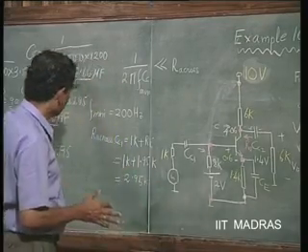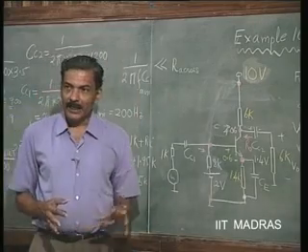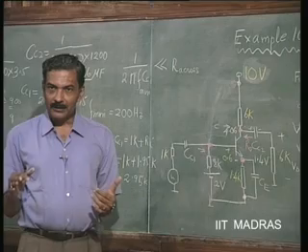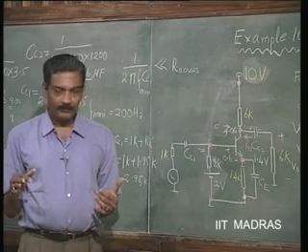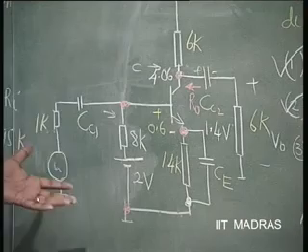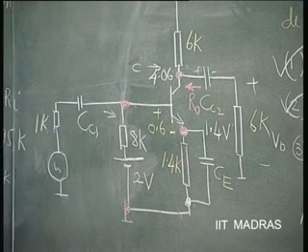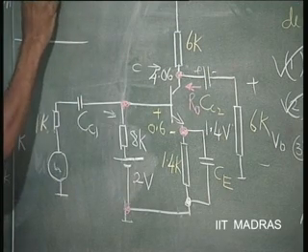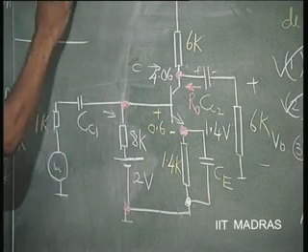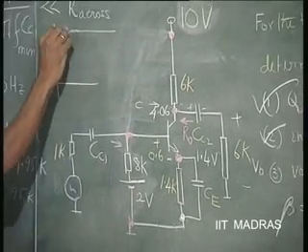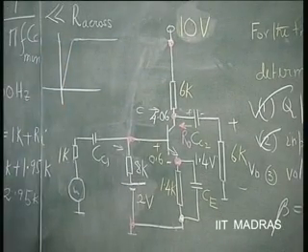So, they will reduce the gain, and that will bring about a poor lower cutoff frequency. If this kind of design is done, it will assure that up to 200 hertz the gain is not reduced at all. So, these coupling capacitors bring about a lower cutoff frequency in the amplification factor. So, the amplification will not be 114 up to very low frequencies, because it will be 114 up to about 200 hertz.